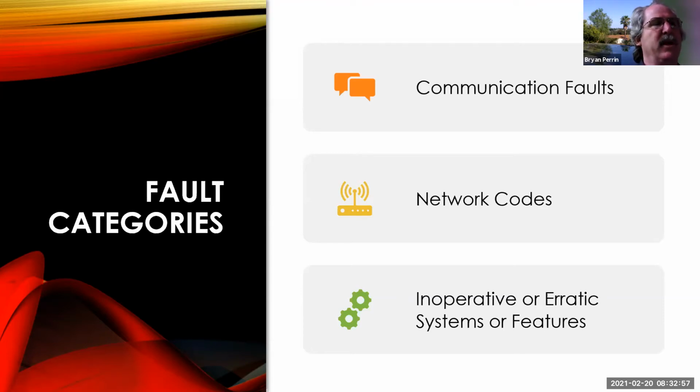So if I have communication with all the modules and network codes, then a network issue is one of the options, a possible list. But they don't scream a network fault. So I can have issues. I got some case studies in here where I might have a malfunctioning vehicle that doesn't scream network. I don't have any network codes, but yet it's a network problem.